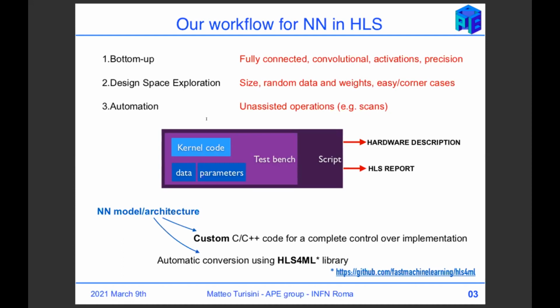I like to work with a high level of automation, so everything is wrapped in scripts for an assisted scan, and I parameterized the size of the layers and which dataset to use in order to explore the space of possibilities with HLS for neural networks.